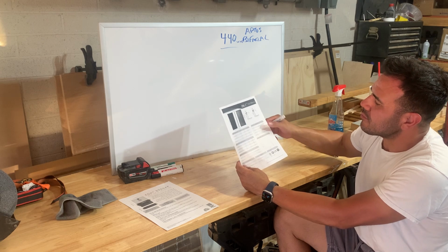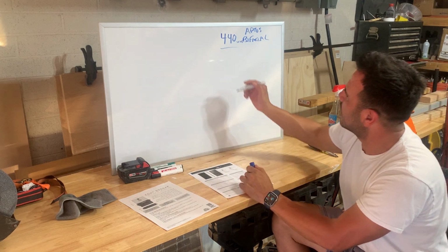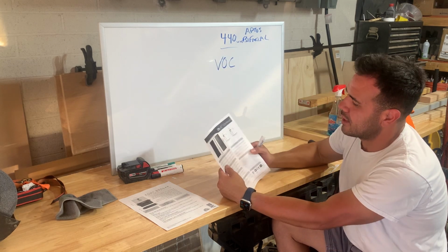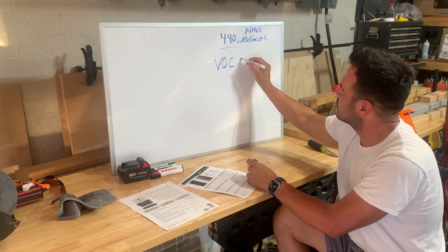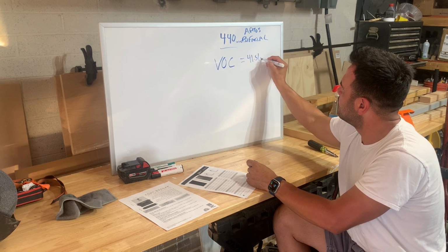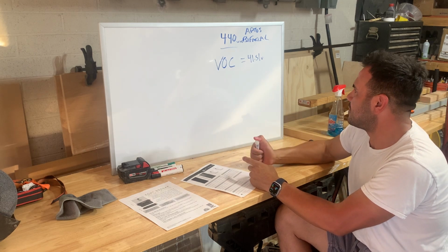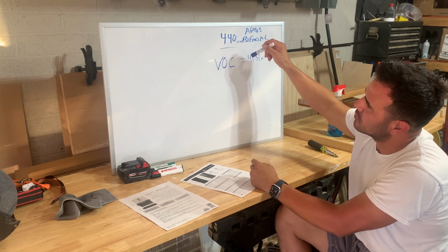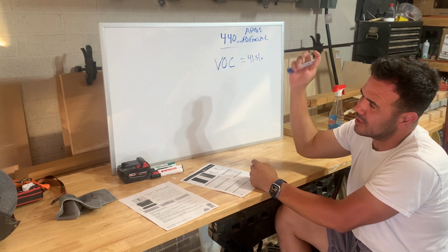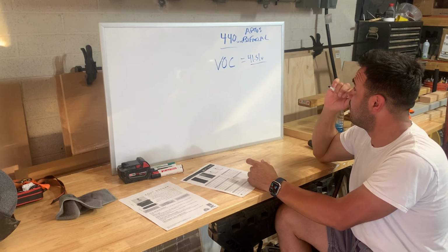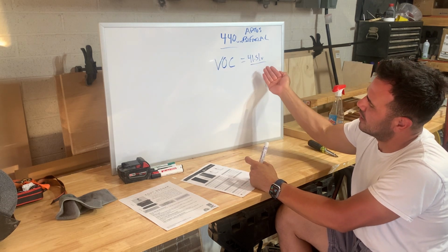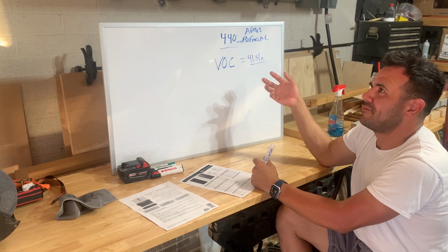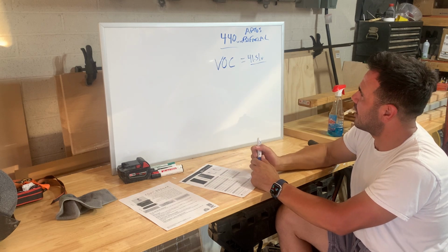The first one that's important to know is the open circuit voltage. For this solar panel, it is 41.51 volts. This number is telling us that the maximum amount of voltage this solar panel is going to produce, with the perfect angle towards the sun at 77 degrees Fahrenheit, is 41.51 volts. But that's with no load hooked up to it. That's with it not being hooked up to an inverter. It's not running anything. That's just the max it can output with no load attached to the solar panel.